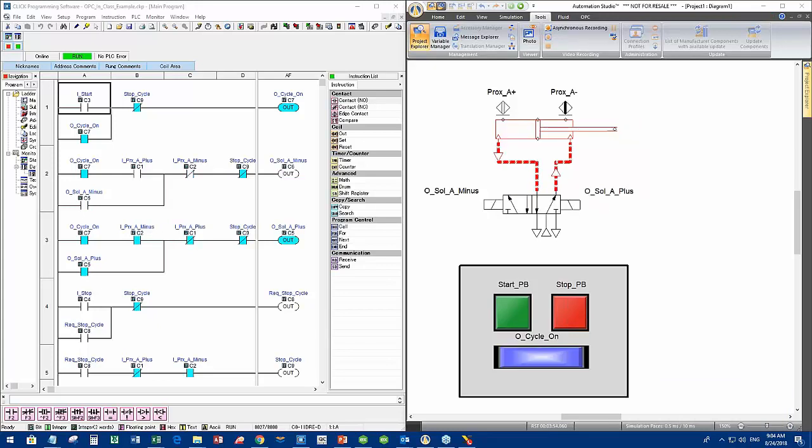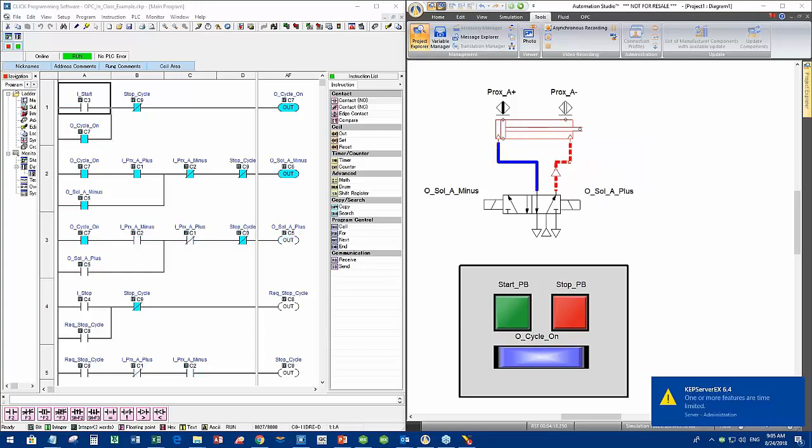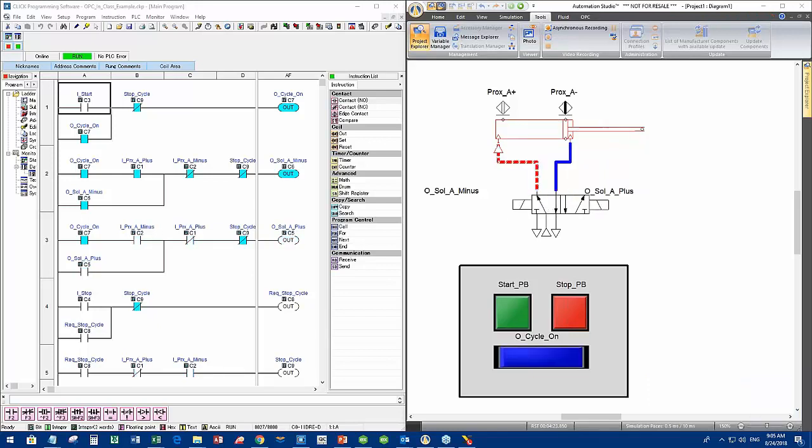So basically what you're saying is, if we create a virtual system, on that virtual system we could have a little image on the right side saying that this variable in AS will be this variable in Allen Bradley, for example. So they have the table of equivalents, and then we supply this file. We say that we use the Kepware OPC server that is free, so they can download that. And providing this, the students would open it and just have to write the logic in the PLC to control Automation Studio. Exactly. Okay, great. That's the way to do it.